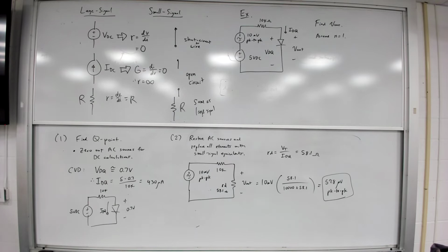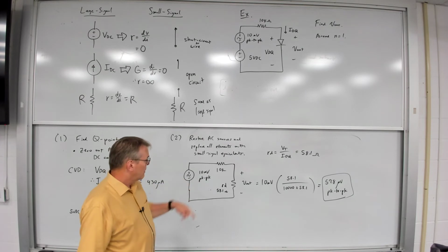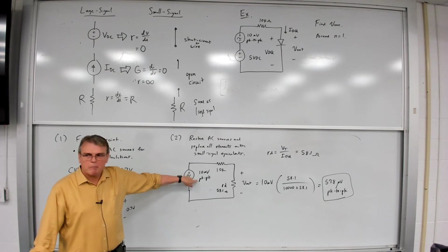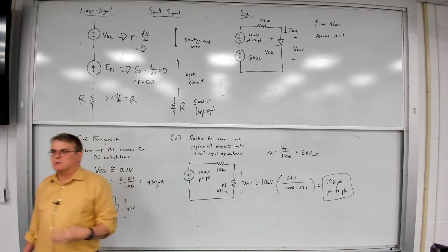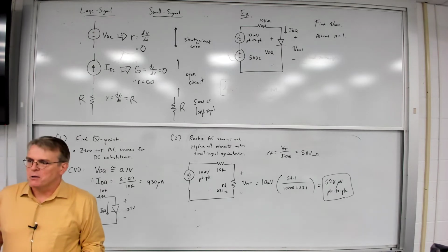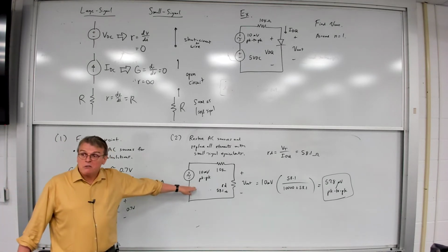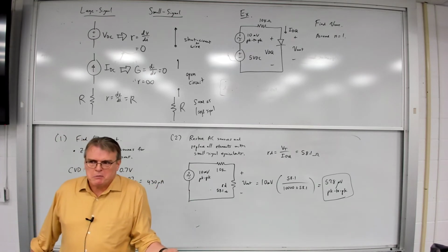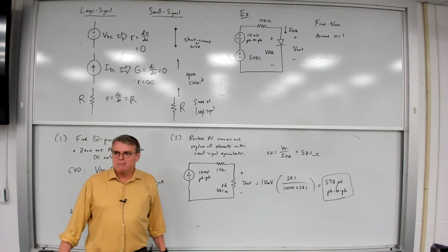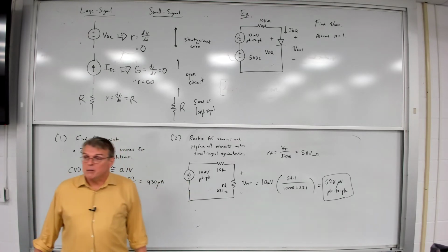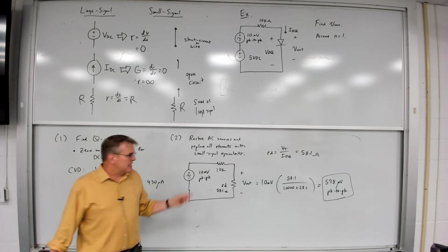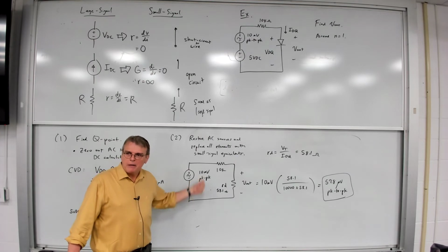We can just treat the AC source as one side. In other words, I'm treating it as a 10 millivolt peak-to-peak signal, so I know my output's also going to be a peak-to-peak answer. This is going to be some type of perhaps sinusoid. It could be some other type of periodic AC waveform. I'm assuming it's sinusoid, but whatever it is, it's 10 millivolts peak-to-peak. It could be a voice signal with a peak-to-peak value of 10 millivolts, right? It could be anything. I'm just saying it is an AC signal which is very small compared to the DC values.